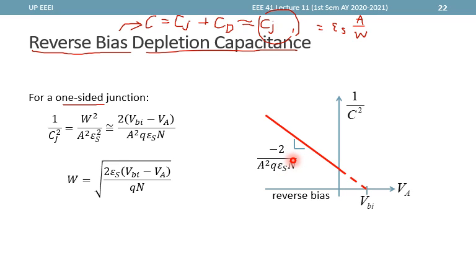So when we have our diode already fabricated, what we can easily measure is not the doping concentration, not the built-in voltage, but rather say apply some current and apply some voltage. Now if we apply some small signal voltage, and if we check the small signal current, then we'll have some idea of the small signal resistance and small signal capacitance of the diode.